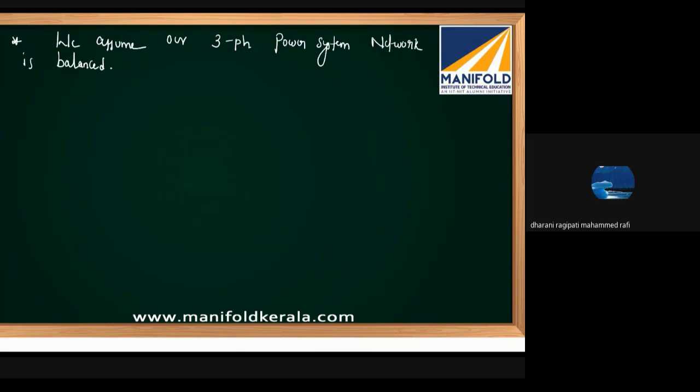So in a balanced system, we know that the currents and voltages are balanced. That means their magnitude is the same, but they are separated in time by 120 degrees. So rather than doing the analysis in all three phases, we do the analysis in a reference phase, that is A phase, and we use the same results for the B phase and C phase. That reduces the analysis. Otherwise, doing three-phase calculations every time is a lethargic process. So we assume our three-phase system is balanced. With this, what advantages do we get?